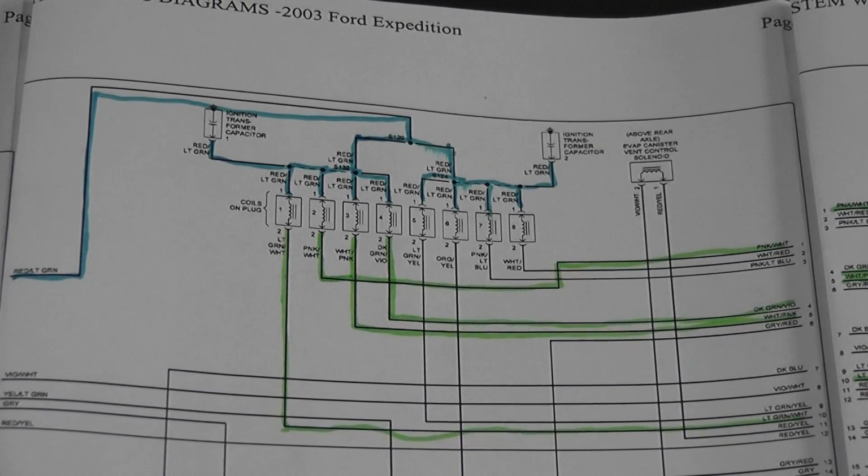Okay, so this is a coil over plug engine. I've shown a video previously on a Ford coil over plug system with a misfire, where we access the coil primary current ramps from the fuse box. So that was our goal with this one, is we want to do the same thing. We mapped out the coils, and what we found is this one's a little bit different.